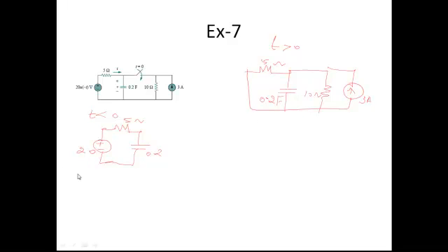So now again, as usual, for the first circuit you need to find out what is Vc of 0. You have to apply that for the second circuit. Okay. So what is Vc of 0? As usual, you need to assume it has been in that state for a very long time, so it attains the steady state condition. The capacitance will act as an open circuit. Under open circuit condition, the entire voltage will appear across the capacitance. So Vc of 0 will be equal to 20 volts.